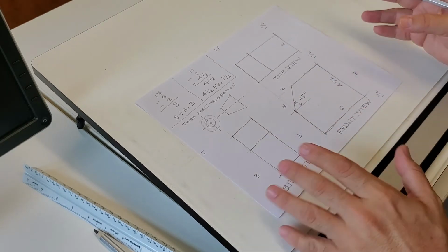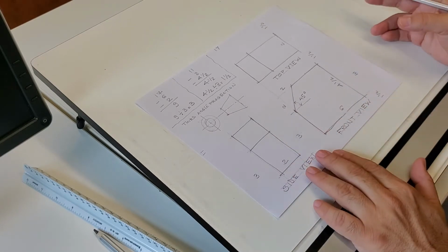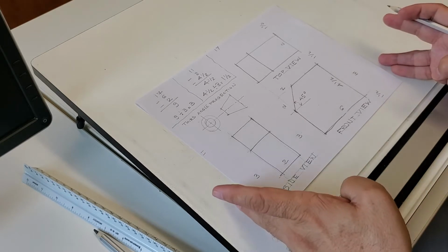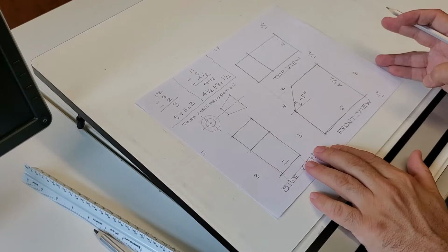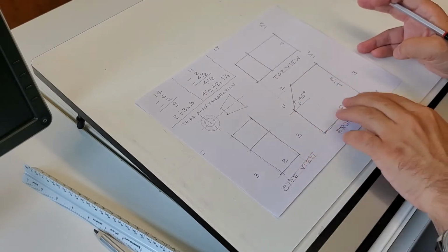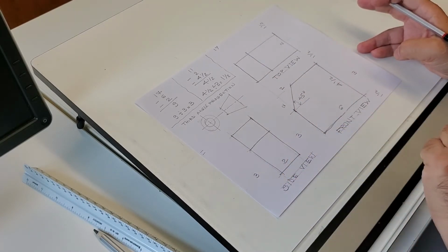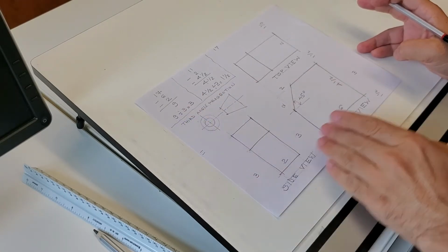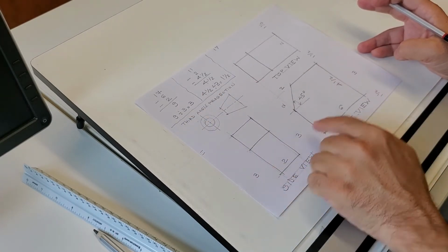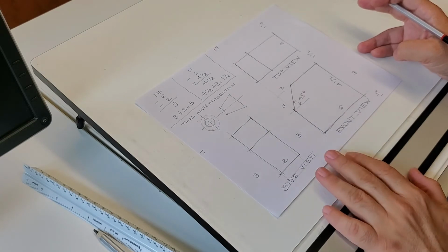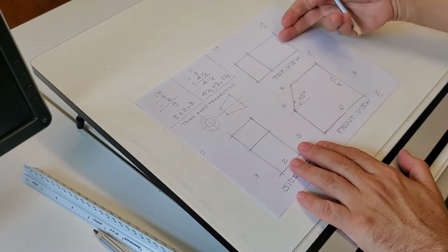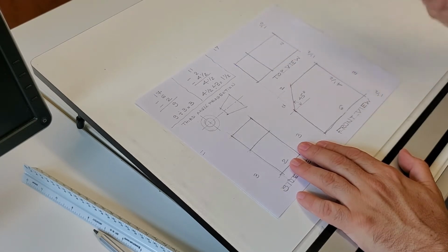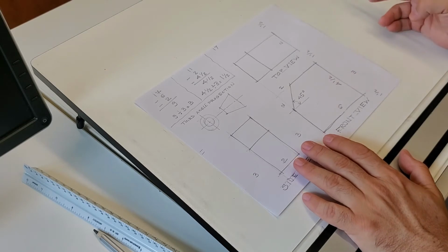Now let's go and calculate the spaces between them. If we take the width of the paper, which is 17, we subtract from it 2 and 6, we end up having 9, divided into 3 parts. Every one of them is 3 inches. Vertically, we do the same thing: 11 minus 2 minus 4.5, divided into 3 parts. We have 1.5 for each space.